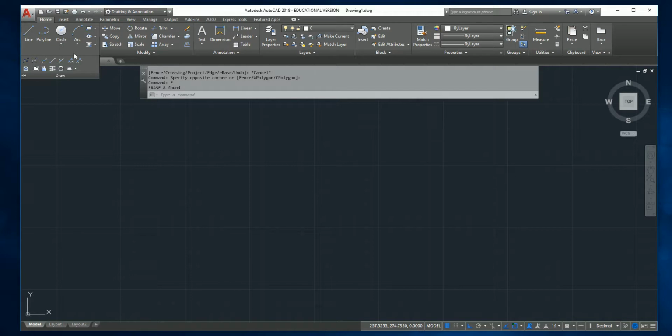So ortho constrains you to your Cartesian coordinates. So it constrains you to this, right? Perfectly horizontal, perfectly vertical. You could change it so your ortho will set every 10 degrees. But they have polar tracking for that, so you don't necessarily need to.